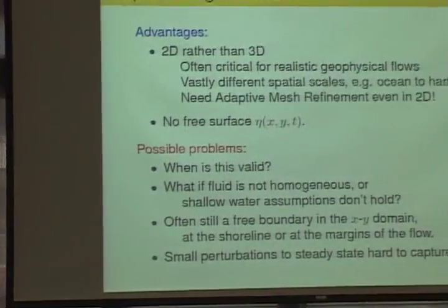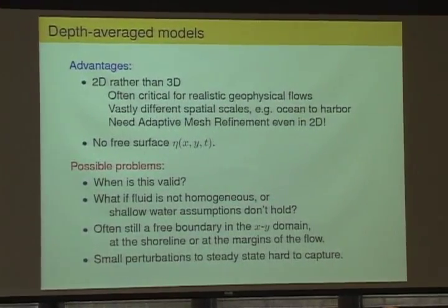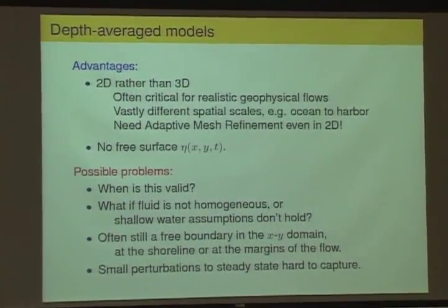It's not always clear that these depth-averaged equations are accurate enough, and in some cases you might want to switch from a depth-averaged model to a full 3D flow for detailed analysis of some part of the flow. But it turns out that for a lot of problems, these depth-averaged equations give a pretty good approximation.